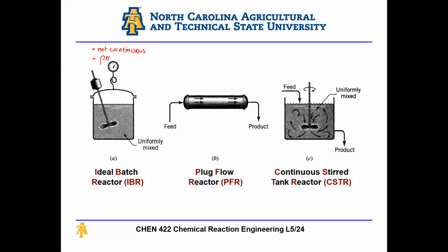And perfectly mixed, right? These are really the two things you need to know. A PFR: I have feed going into a tube, and I get products on the other end. Here we assume they're like plugs pushing each other, and there is no mixing, and it is continuous. These are the two main properties, besides its operational properties.